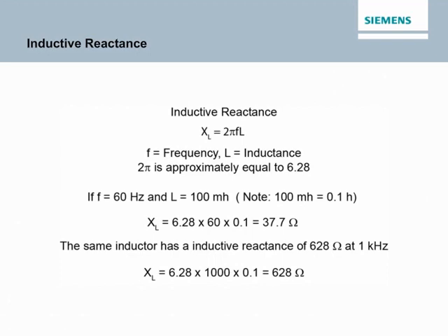Inductance affects current flow when the current is changing by producing a counter EMF, which is a voltage that opposes changes in current. In an AC circuit, current is changing constantly. Inductance in an AC circuit, therefore, causes a continual opposition to current flow, and that's called inductive reactance. As shown in the accompanying graphic, inductive reactance is equal to 2π times the frequency times the inductance.